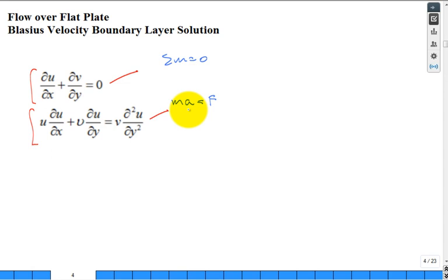What is F equal ma from your dynamics? Newton's second law. It says that if I have an imbalance in the forces of my object, what can happen? The object can accelerate, decelerate. I can have a change in the momentum, the linear momentum of the system. Well, as I've written it here, what is this term? That's some sort of forces through viscous shear stresses, forces per unit area. And what can it do? It can slow down or speed up the flow. It can change the linear momentum of the flow. These equations are pretty abstract mathematically, but they're pretty easy to understand, hopefully conceptually.